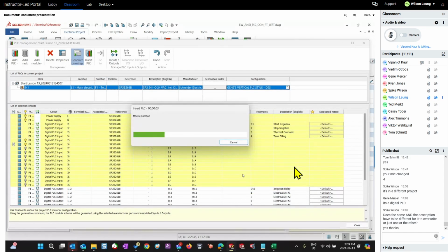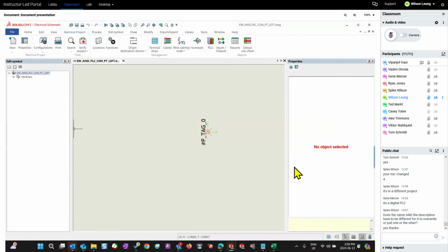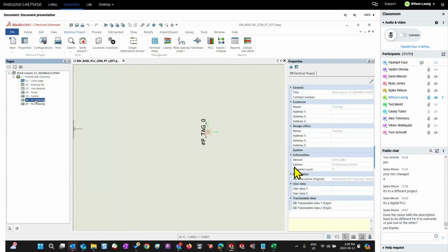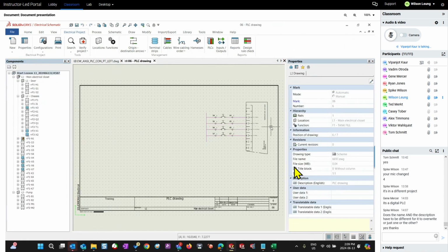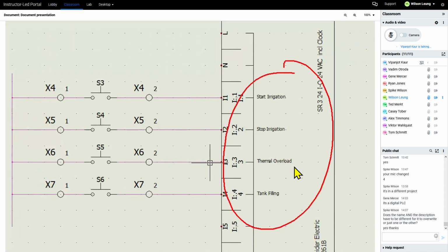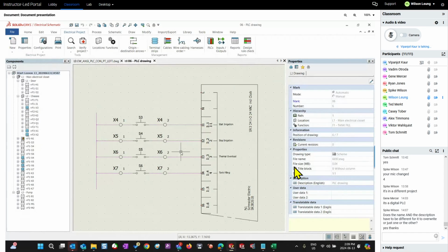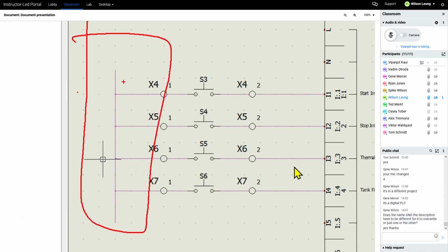But there's going to be one problem because I'm using the same macro for all the inputs, the same macro for all the outputs. Get to your documents tab, double click, open your drawing. See, on the right of the page, my descriptions are here. Each and every input is using this macro. This macro had an insertion point on this side, which is why it snapped it. So if that tells me, Vip, I'm going to put my symbol for inputs on the left of the page, then these macros will not work for you.